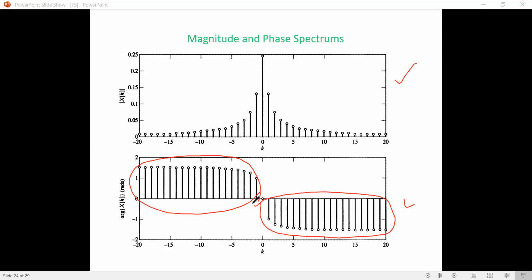Whenever we are using a signal, we can easily understand what frequencies are present there. Although at larger values of k, that means higher frequency components, will have progressively lower amplitude. For this reason, when we are designing a system to handle this signal, theoretically infinite bandwidth will be needed.